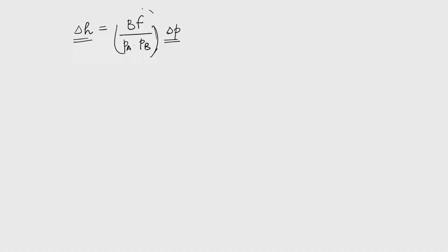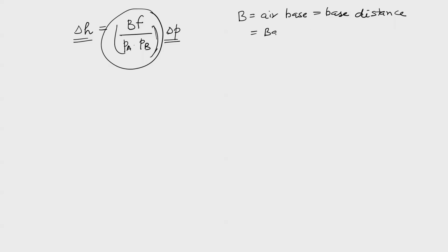If I multiply the parallax difference by this term here, I can get the height difference, where B is my air base, again I repeat, or the base height, or base distance, also called the base, right.